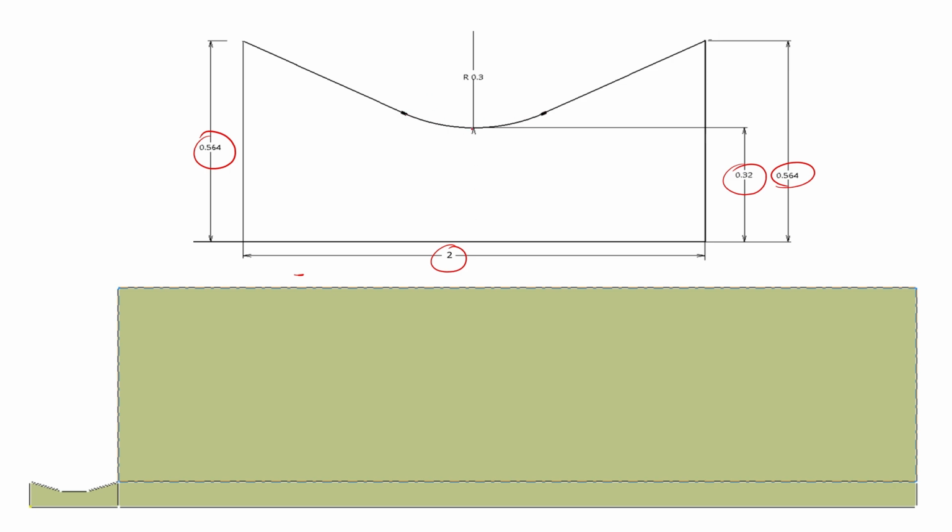Just to give a smooth flow in the throat section, I have given some radius here. Okay, so this is the CD nozzle. Then to that I have added another flow domain. So here I have taken more than 10 times the CD nozzle length along the length.